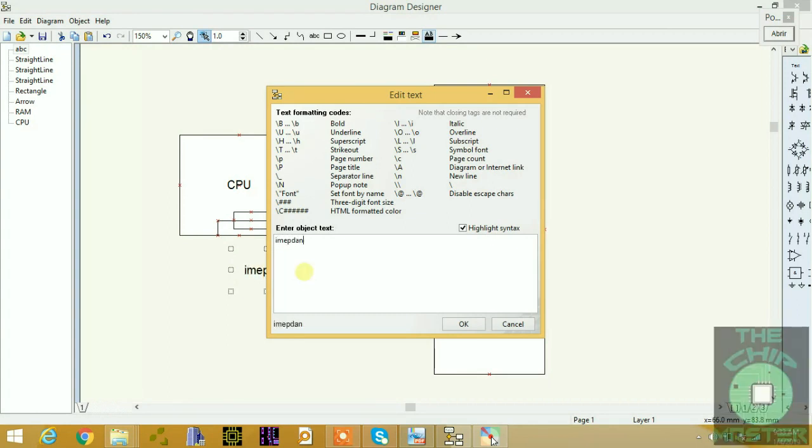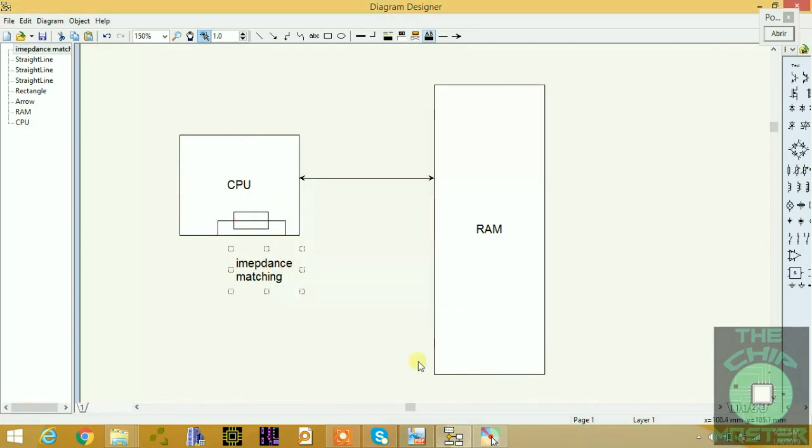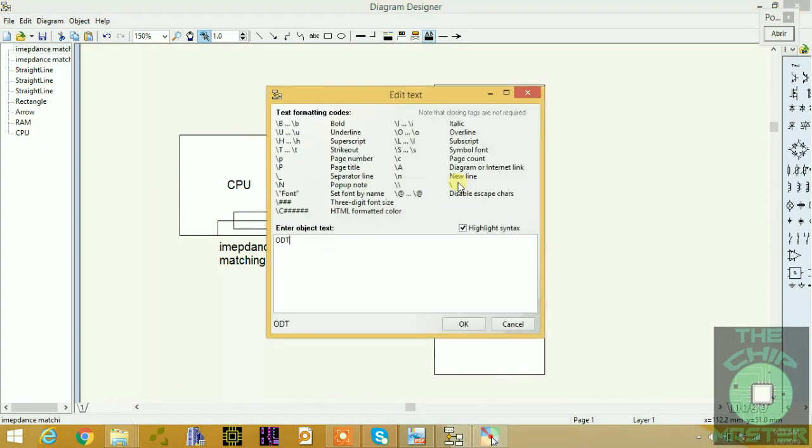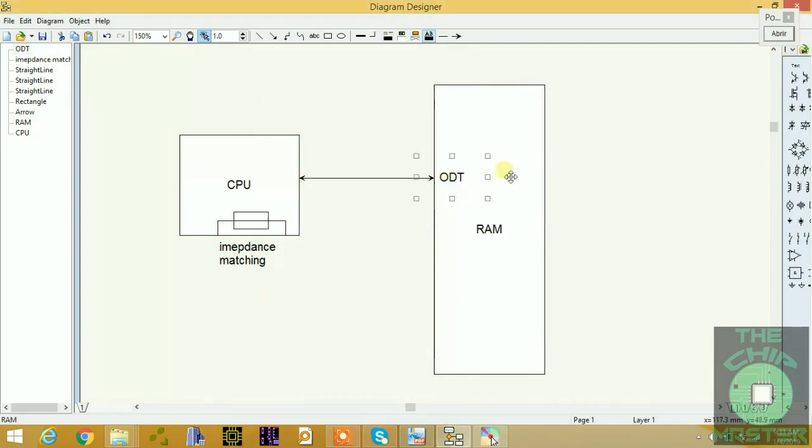impedance matching, right? To prevent signal reflection, so you don't lose your data. So that is why it has a termination resistor, the on-die and ODT section inside of the CPU and the RAM, to maintain that data so you don't lose it. Otherwise it can cause all different kinds of indescribable faults such as hanging, blue screens, all different kinds of problems, because there is a fault with your termination section on your RAM, or during the transmission of data, right?